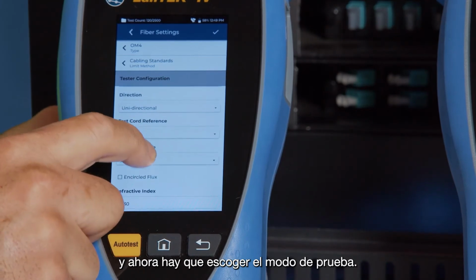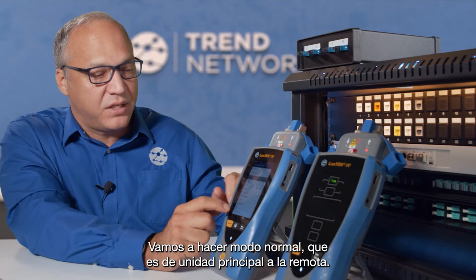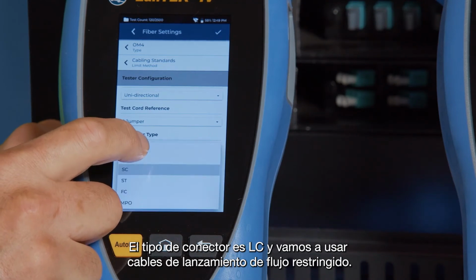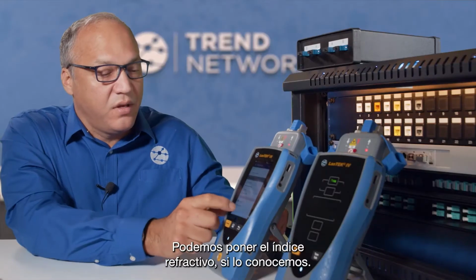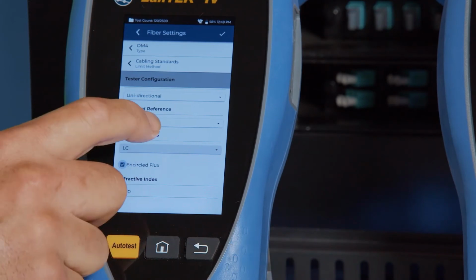And now we need to choose the test mode. So we're doing normal mode, which means main handset to remote handset. We're doing a 1 jumper calibration. That's fine. The connector type we're going to test is LC, and we're going to use encircled flux launch cords here. Okay. And the refractive index, if we know it, we can enter that in here.